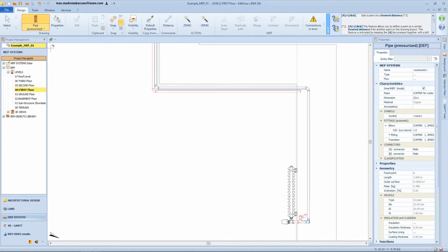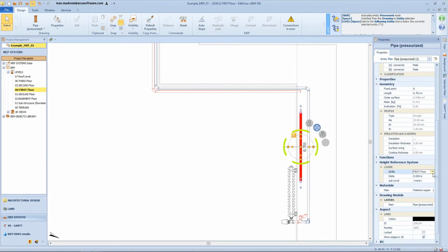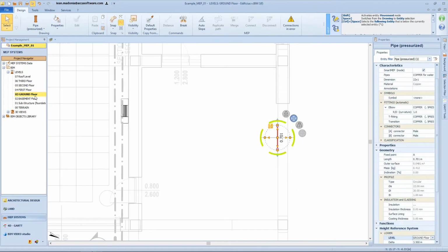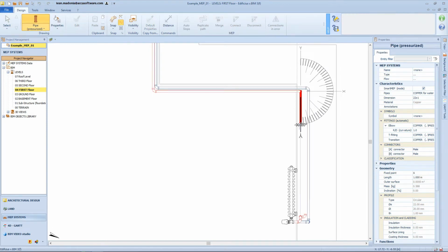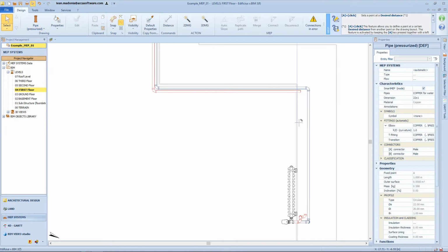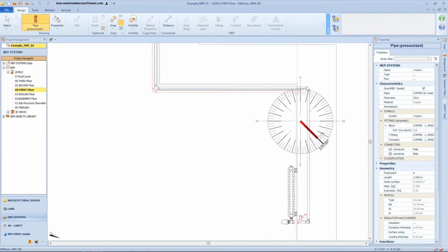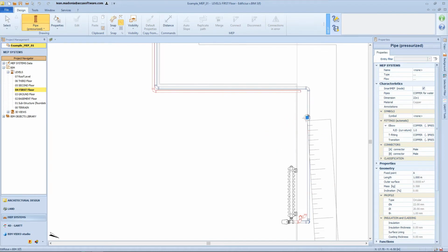In plan view, the level assignment is not supported using the same menu that instead appears in 3D, as the pipe will belong to the level on which it is being modeled, and once completed, it can be assigned to another level when necessary. Since you are working on one level, you can model the pipe only on horizontal planes. Therefore, since the plane is already fixed, the directional cube does not appear to choose other planes but only the protractor. It is not possible to work with a section view of the plan but only with the view of the level.